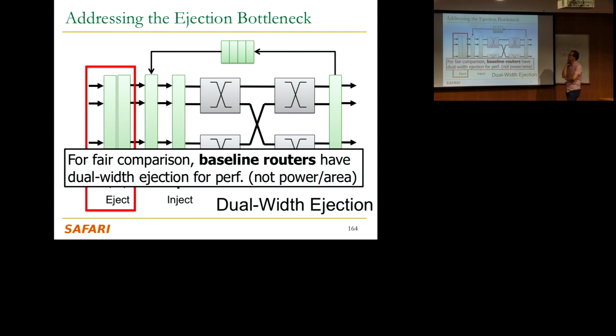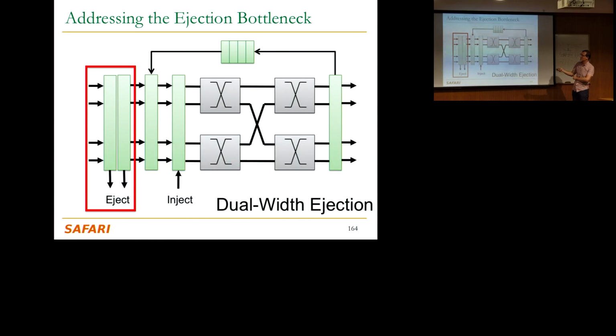Yeah. The problem is, once you take things out of the buffer, you need to have a way of going through this permutation network again, right? And the easiest way we could do it is basically injecting again into the router. I think if you want to get rid of it quickly, you need to have some separate path somehow. We didn't look at that path. Right. I think that's the downside. Once you take it out, putting it back in is not hard. It's not easy if things are flowing into the router. But I understand what you mean. So we looked at one flit router, which buys you something. So 4 flit buffers is good, but we don't immediately take it out. We take it out when you can. Okay.